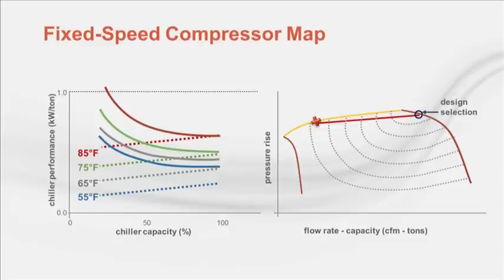Note that it is important to ensure that centrifugal compressors can unload to a low operating point at this design entering condenser water temperature to ensure the unit does not surge in the event of a system issue. Since the surge boundary is established at full speed operation, the surge point is important whether the unit operates as a fixed speed or variable speed chiller. As a result, many engineers specify this unloading requirement on behalf of their customers.